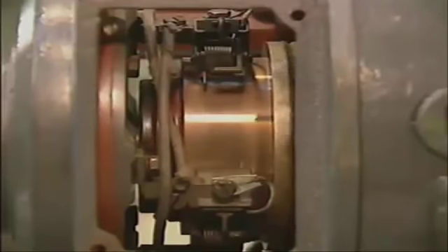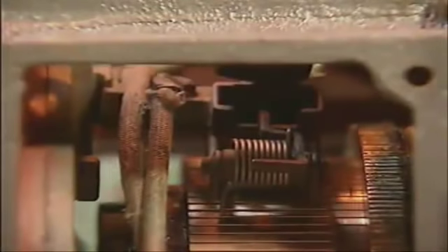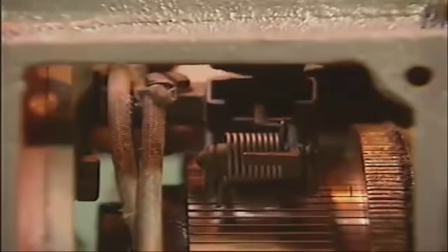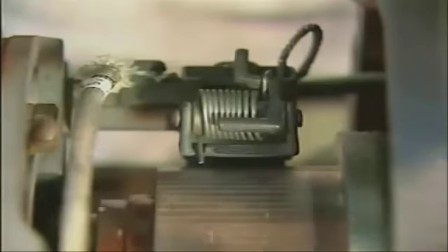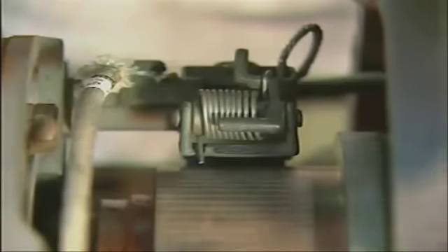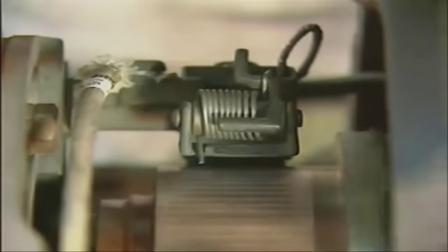Brushes make the electrical connection between the power source and the commutator in a DC motor. Brushes are usually made of carbon, and the size of a particular brush is determined by the amount of current it has to carry. Many of the problems that occur in DC motors originate in the brushes or in the brush rigging assembly. Two main causes of brush problems are wear and damage, both of which can be caused by improper adjustments. To do their job properly, the brushes must make full flat contact with the commutator at all times.